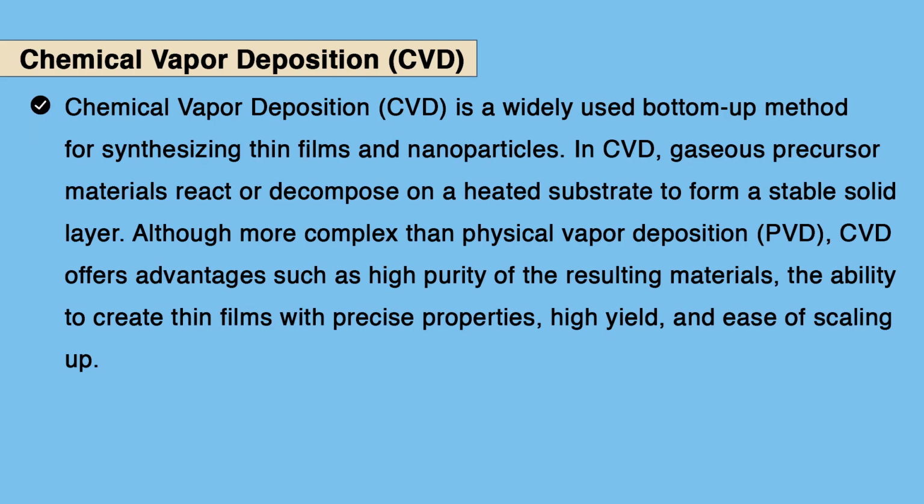Chemical vapor deposition, also known as CVD, is a widely used bottom-up method for synthesizing thin films and nanoparticles. In CVD, gaseous precursor materials react or decompose on a heated substrate to form a stable solid layer.